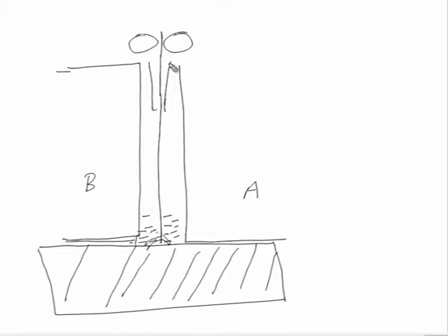This arc in the initial stages leads to the melting of the flux in the beginning, and once the melting of the flux takes place to such an extent that the electrode wire with the arc is completely filled in and covered by the molten flux, the flow of current starts through the molten flux.